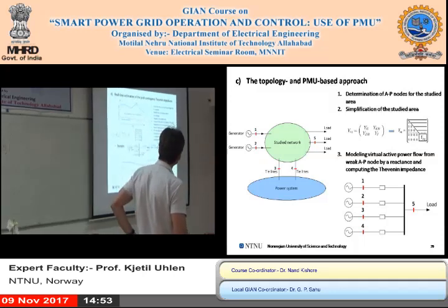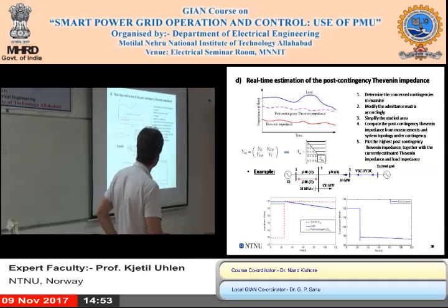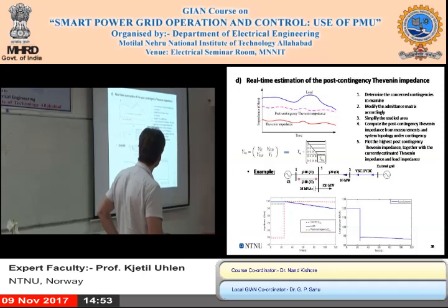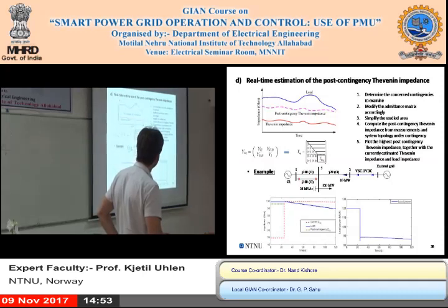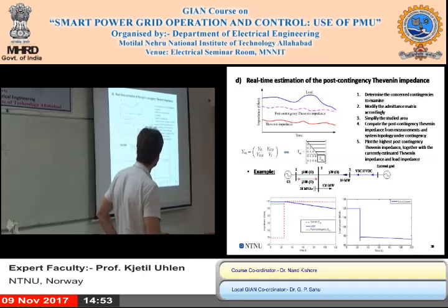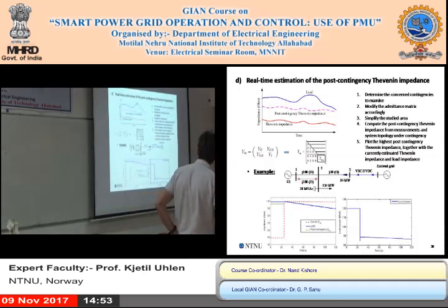So this is then a sort of recipe for how you would do that. Essentially, you would plot the Thevenin impedance for the case with the highest impedance. That is sort of illustrated here. If you have an intact grid here, it's easy to see that the impedance of this is the parallel of these lines, more or less 100 ohms.